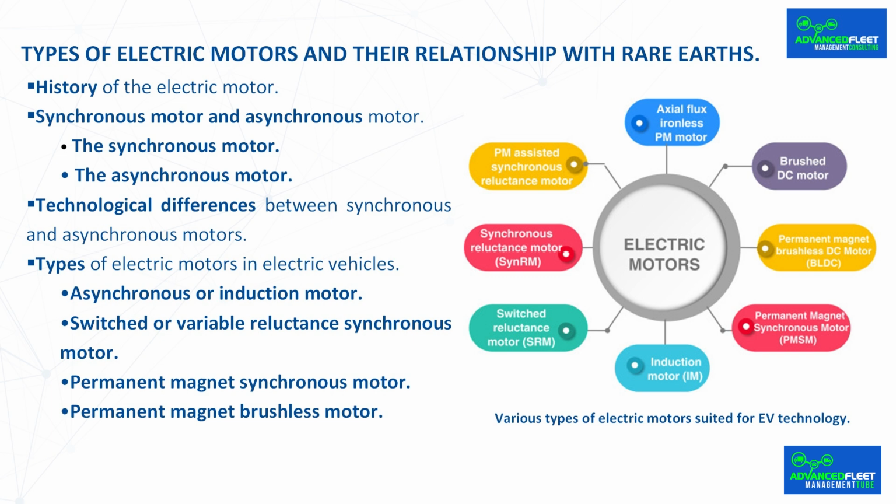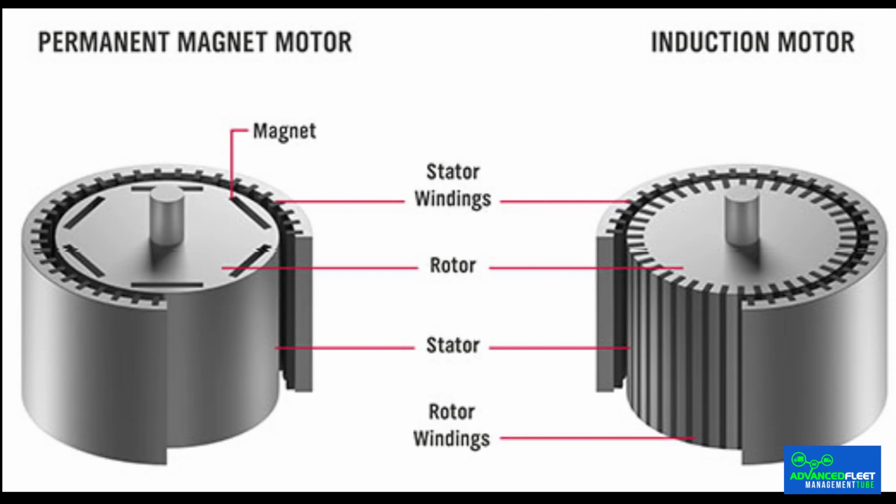During the startup phase, a significant difference in rotational speed is observed, which translates into a significantly higher torque. Once the motor reaches operating speed, energy consumption is minimal. Controlling an induction motor is more complex compared to a permanent magnet motor. The calculation of the voltage and frequency required by the controller is carried out by using mathematical vectors, which is known as vector control.